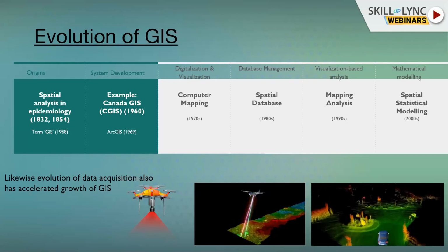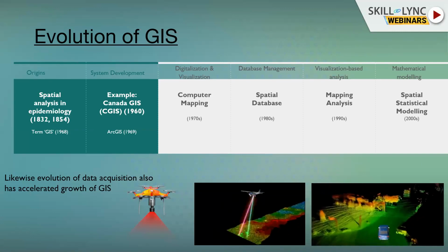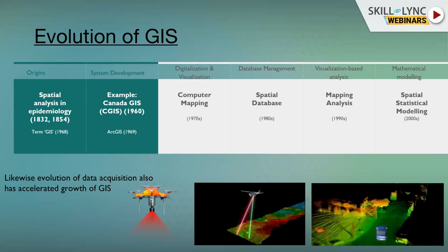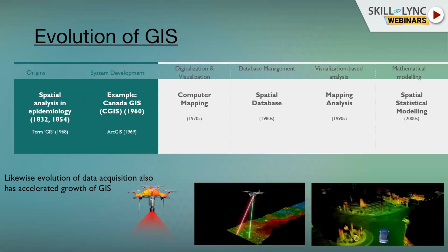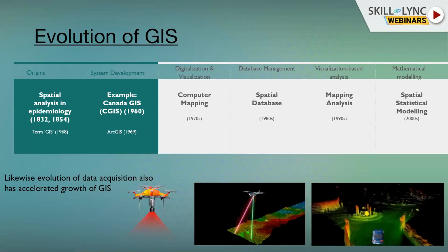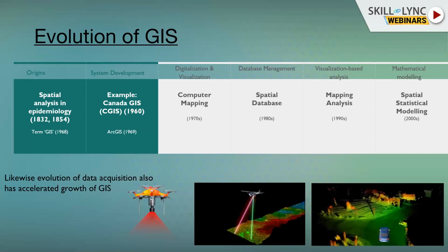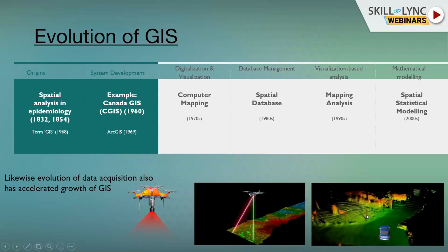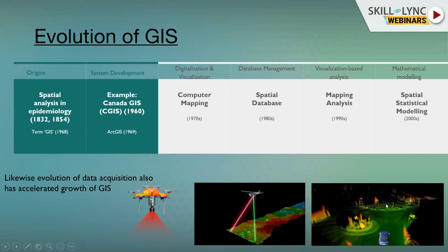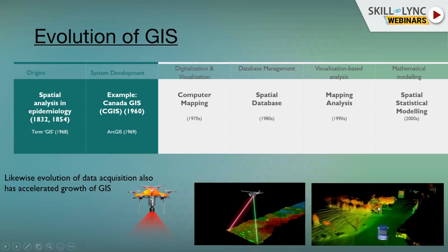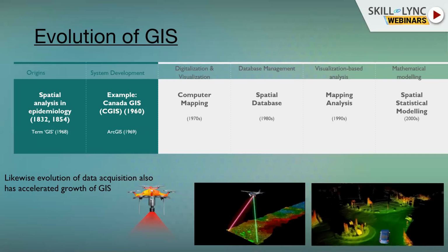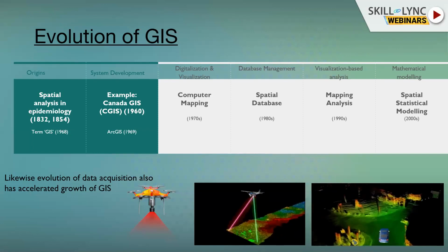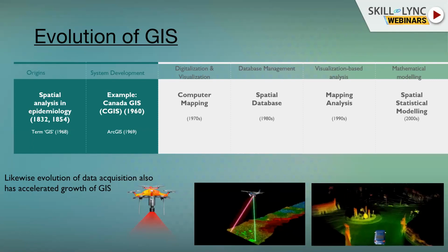Lidar data is the current buzz for GIS, because it's able to give you more accurate data. Like, if you just want to apply lidar onto utilities, if you just do a mobile lidar survey, and see here, you are able to see the sag in the electrical lines, right? You're able to see the sag. So it helps you understand the risk, and whether it is acceptable for the transmission line to come that low. So that is the accuracy lidar is going to give.